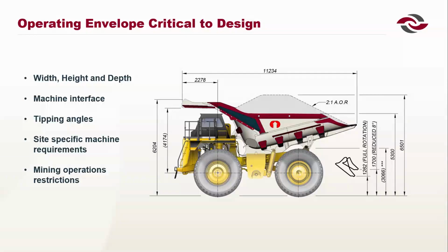Finally, axle split compliance once again comes into play. If the tray geometry causes too much weight to shift forward or backward, it overstresses the tires, suspensions, or brakes. OEM axle load splits must be respected. The operating envelope is not an afterthought. It is a boundary that ensures a tray is not just productive, but safe and legal to operate.